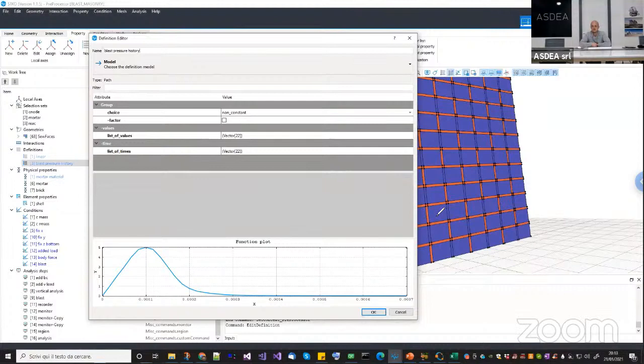Now, I do not recommend starting with explicit right away because it is a very difficult topic. Your analysis should be really fast, in the sense that it should be a fast dynamics. You cannot think about doing, for example, a structure interaction under an earthquake, so you have one model with millions of elements for several seconds of analysis. It is something that will take days and days. So you have to start playing with explicit solution and try to understand how it works.